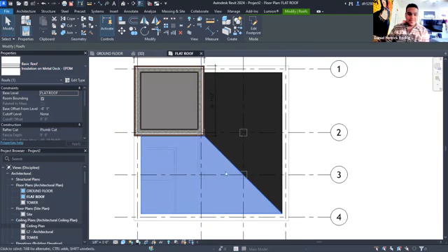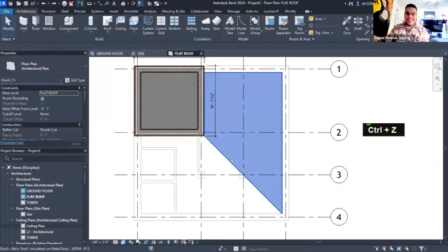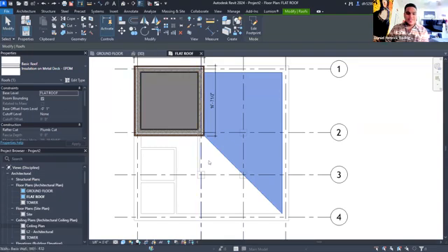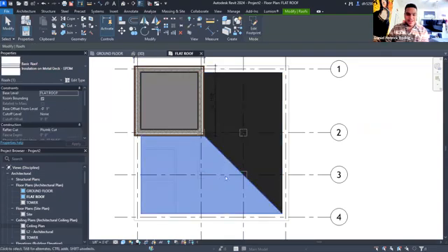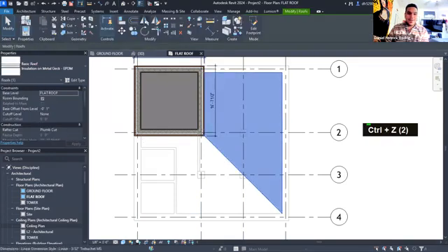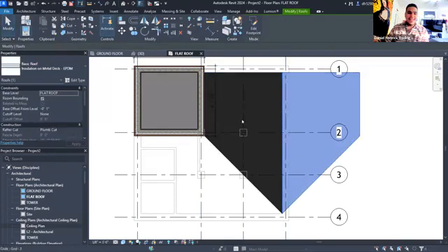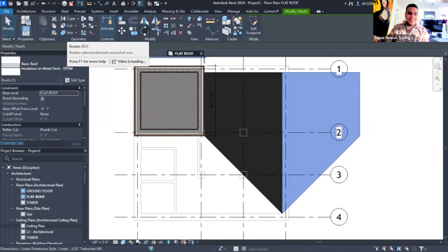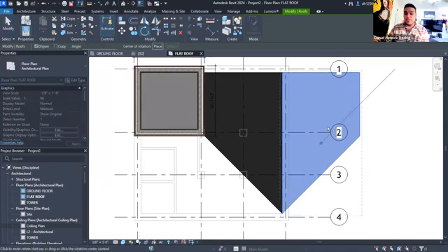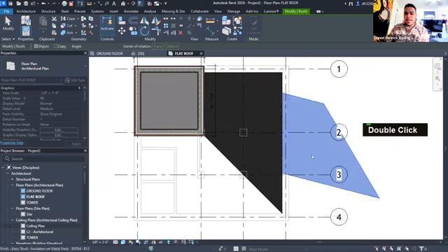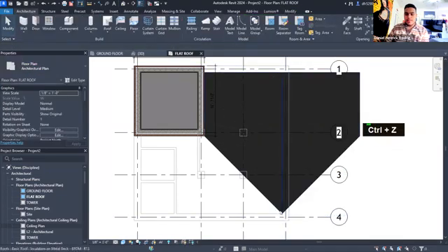I actually just realized this because, let's do it how I do it on the guide, because on the guide I also show you a different tool. But yeah, you can just mirror it by this side, or we can mirror it from this side, and then we can use the rotate tool here. And the rotate tool is going to usually rotate from the center of the object, but you can click on this button here to place a center of rotation, right? So I rotated it here, but I don't want to spin it. I want to actually rotate it by the tip of it here, so I can displace it.